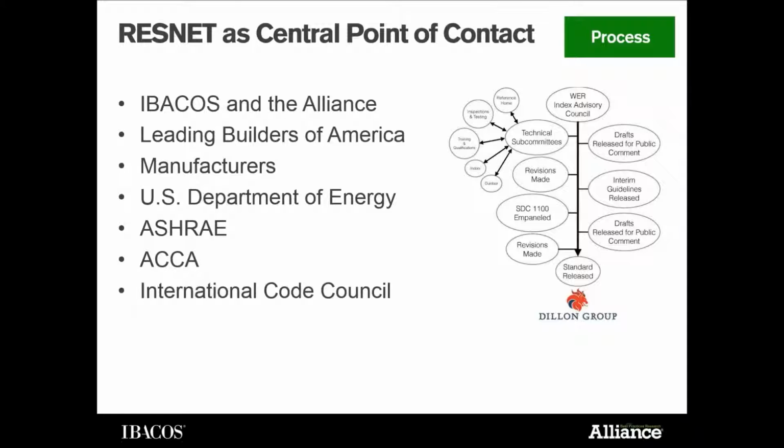So understanding that there are going to be those outliers, but this is really about the ability of the home to provide that central area of comfort, meaning the bulk of the hours inside some defined comfort envelope, but also the ability to stretch that envelope. I believe the envelope isn't the same for everybody or for every house, and so the envelope that we typically see on the standard 55 chart may not be the same shape for everybody. It could be squat and long and short, or it may be skinny and tall. Yeah. And I think the ability to change that envelope and apply this factor is going to be part of what we look at.